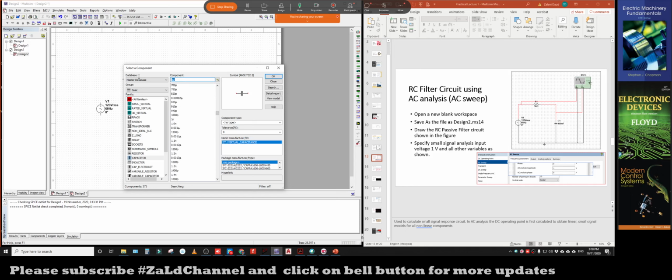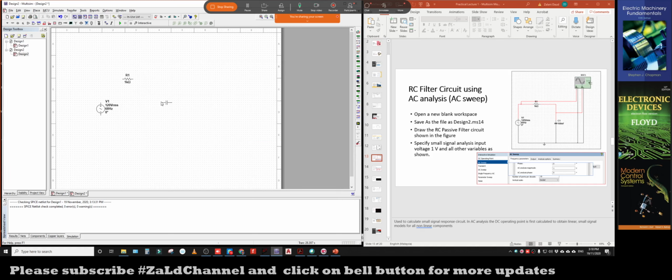Now my capacitor is horizontal. I'm going to rotate it vertically, like this. I push Control R to rotate it. Place this component. Then another one is the ground. We have ground here. Place the ground. Then finish. So we have placed all 4 components on the canvas.